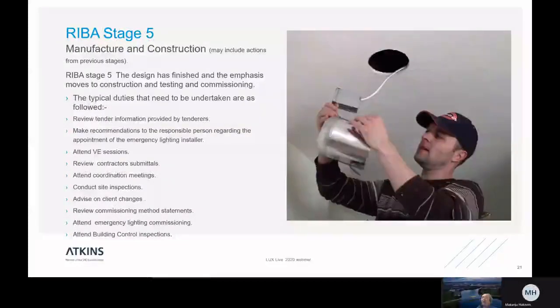And I would suggest to you the better way of doing that is not to convert luminaires and is to provide a separate battery changeover device next to it that runs the luminaire rather than converting the luminaire, because you will not get all the information that you require under BS 60598-2-22, the submittals, the length of the LEDs, all the thermal arrangements from these manufacturers. It becomes difficult to do there.